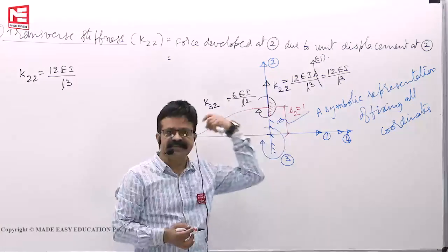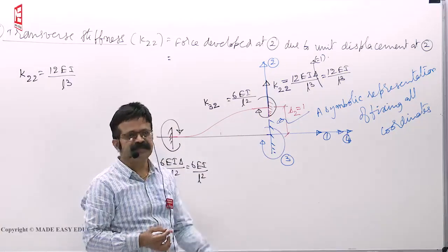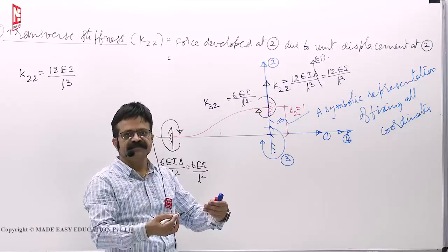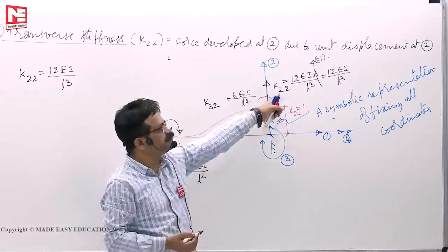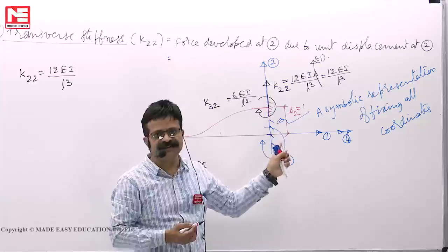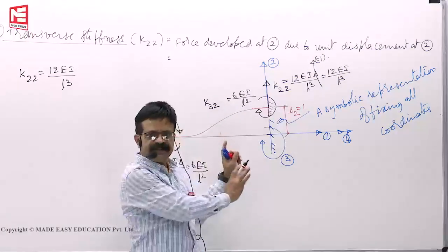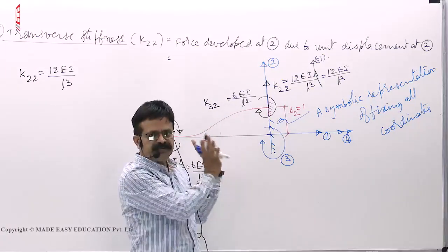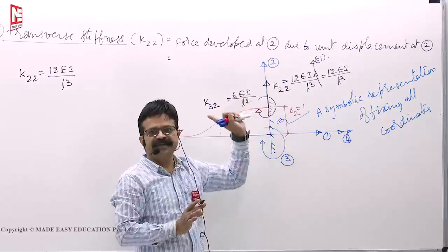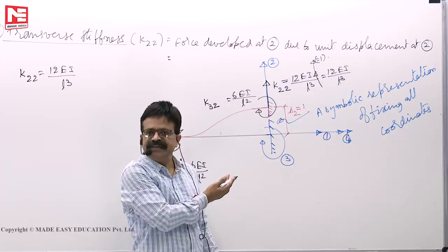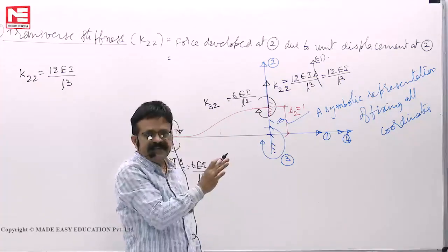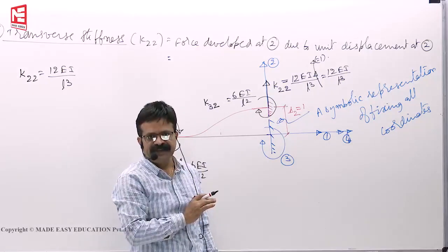Finding the strain energy itself will take again 3-4 minutes. Then double differentiation, you will get the displacement, you will get the force. That much time you cannot afford. You must do the way I have told you. You have to remember 12 EI delta by L cube because so many problems we have done in MDM. So by this time automatically you might have remembered that value.